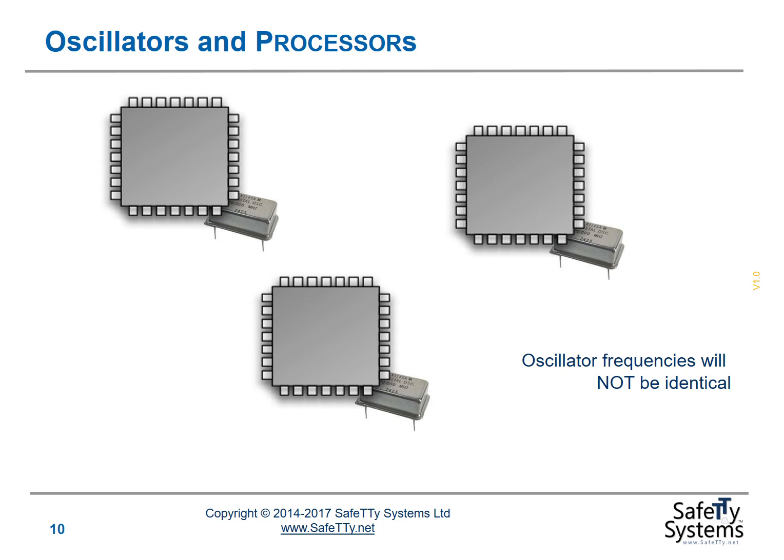So we'll see drift between the processors. That drift will become more extreme if, for example, we run these different microcontrollers with their oscillators at slightly different temperatures. Then we will see even greater drift in the oscillator frequencies. And we will see greater drift in the activities on the different processors.